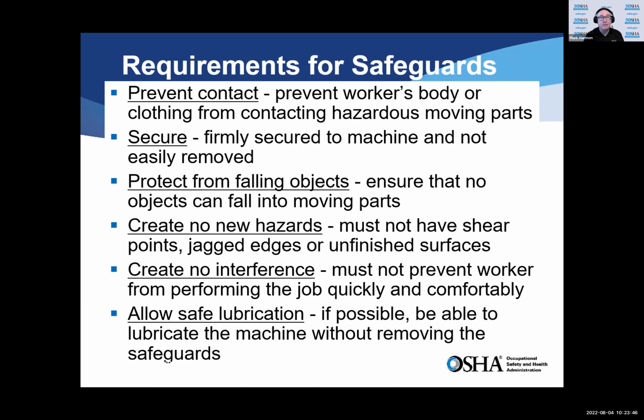What I typically tell people they should not do is weld it or attach it in such a way that it's hard to get off. Because if it's hard to get off, it's probably just as hard to put back in place. If you weld the guard on the machine, with the expectation that it needs to come off to service the equipment, I can almost assure you that they will not weld it back on. They will just discard the guard, in such a way that it doesn't go back on.